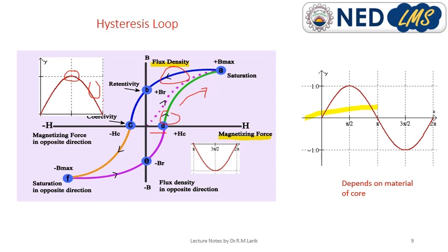Due to the property of that coil, it retains some magnetic field inside. That retained magnetic field remains inside the coil. That's why it does not start from zero. It starts from some initial value, goes to the final value and comes back. So this is due to residual flux. Similarly, there are properties like resistivity, conductivity, and permeability that we must know.